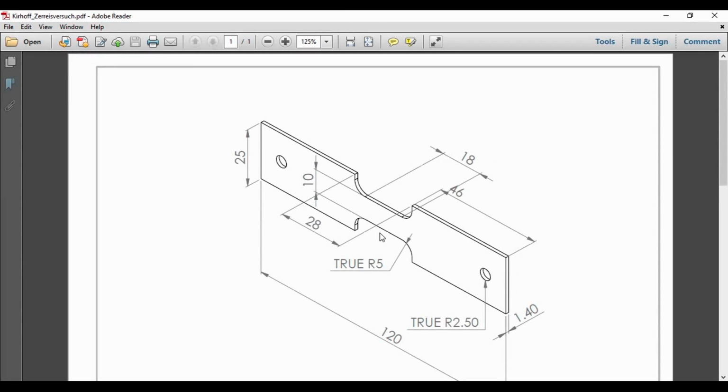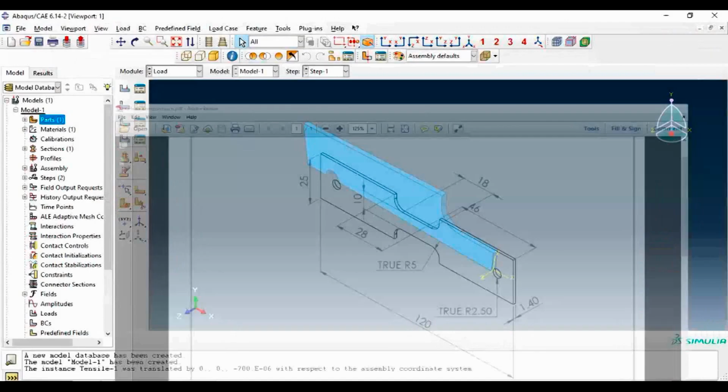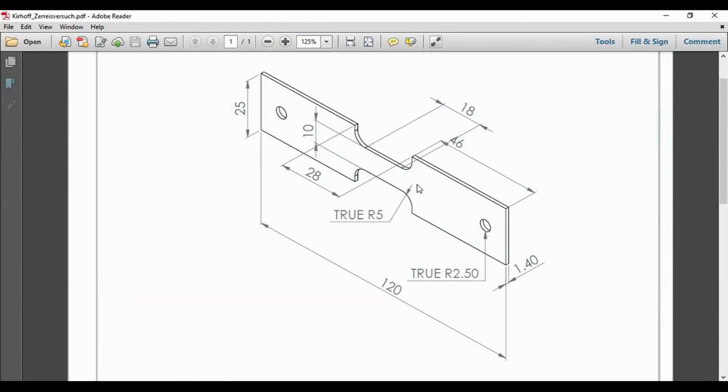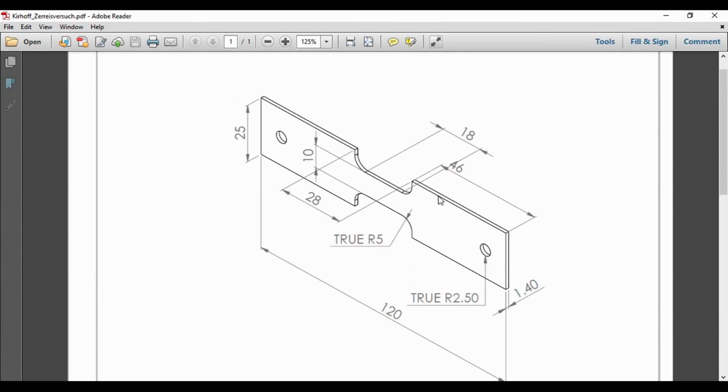What I mean is, forget about the 1/4. Let's go through the complete part and see what is the condition for the tensile test. In actual tensile test, one side is fixed. One of these holes is fixed by the tensile machine, and the other side is gonna be moved through the vertical direction. So one side is fixed, the other side is movable.